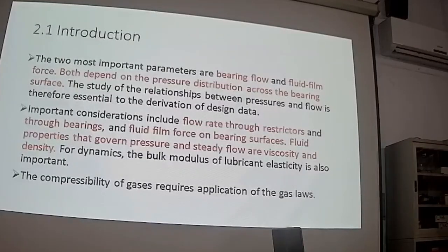So we start to introduce the theoretical background for the hydrostatic bearing. We have lubricant flow and we have a squeezing force in a very small gap. With a high supply pressure, this pressure distribution across the bearing surface can sustain extra loading.